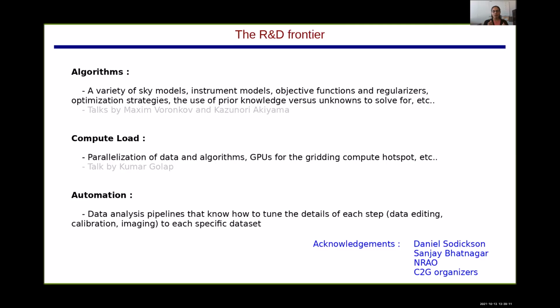Typically, the way we handle what we call interference is by just identifying locations in our data in time, frequency, and antenna space, and simply blanking them out and throwing them away and taking them out from further processing. And so the net effect is a data loss. And a data loss can be translated into a limit on how much your noise can go down. And so that's how that's connected.